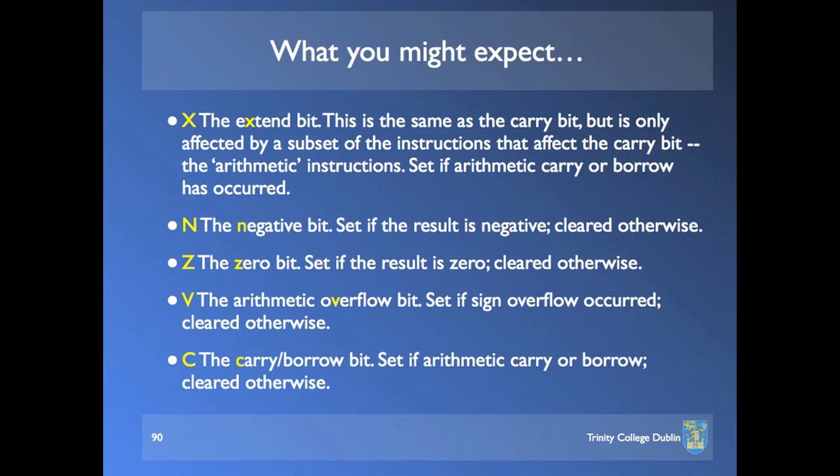Now, if you look at the move instruction, which is a very commonly used instruction, most versions of the move instruction affect the condition code register, and they affect it in this way. You just think about it. Say move. You're moving something from one place to another. The condition code register is set according to the value of the thing that's moved. If the thing that's moved is 0, the Z bit will be set afterwards. If the thing that's moved could be considered negative, if the most significant bit is set, the N bit will be set. If you look at the instruction set summary, unfortunately, I don't have one in front of me here, but you'll see it.